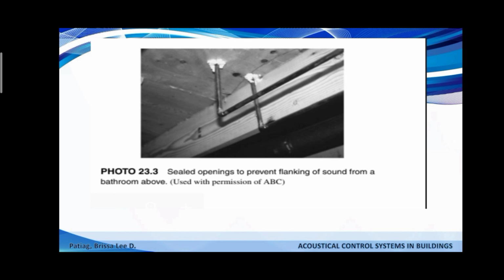So the practical economical limit of the sound reduction through walls is about 50 dBA with the use of background masking noises. This reduction is adequate for most conditions. At the same time, great care should be taken to eliminate as much sound transmission as possible through flanking paths. Air ducts, soffits, and items placed back to back, such as medicine cabinets, electrical outlets, and lighting fixtures, sound transmission through doors and door arrangement, and through window and window arrangement must also be carefully considered in achieving noise control.